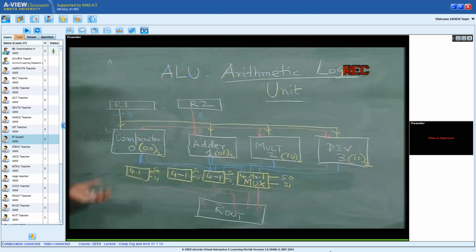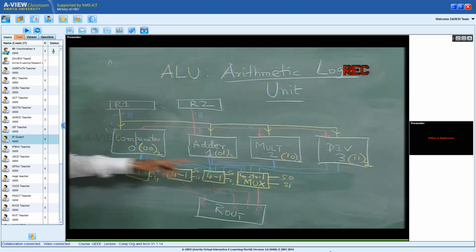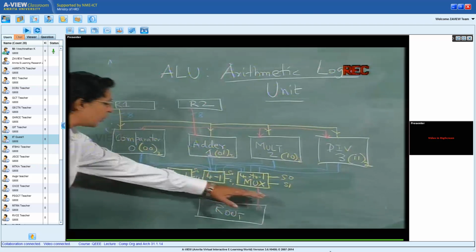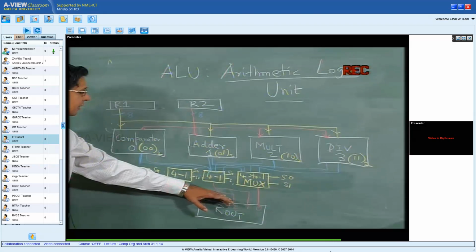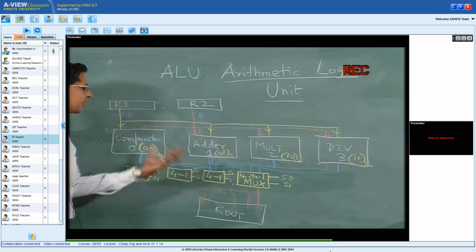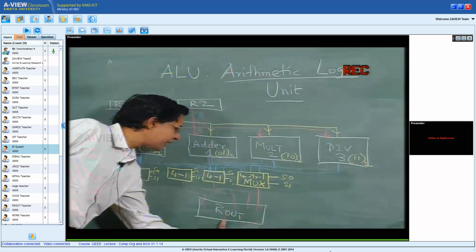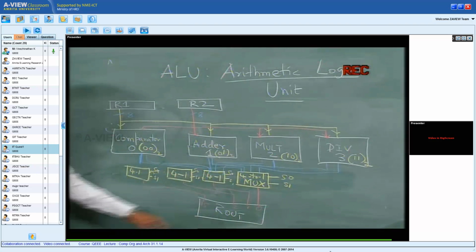And so, if I want to do an addition, I just set this as 0 1, and what will come out is the output of the adder. So, I will have 16 lines in which the first 7 lines are relevant to me. I will take those first 7 lines out and I will get an answer.